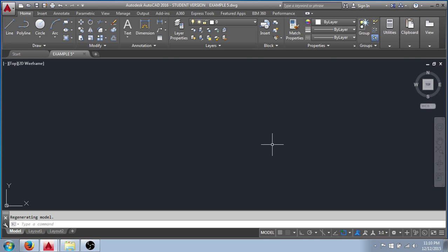And now I'll come in and select zoom extents, which brings it right back down to nothing in this case, because zoom extents sets your view to the graphics that you have drawn. It's like a fit to screen, and since we have no graphics drawn, it just brings it back to nothing. So in effect, it cycles the drawing file through the limits that we've set in that file.